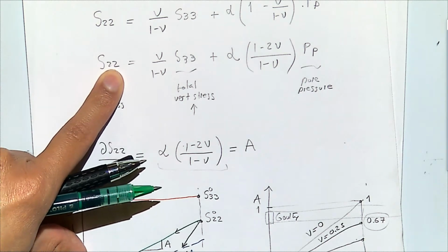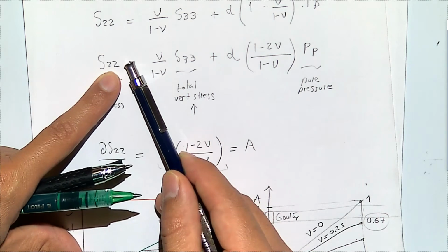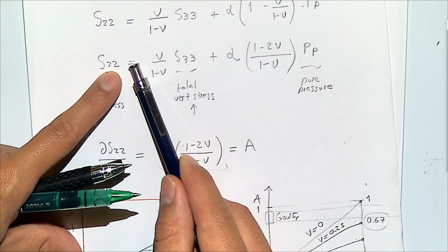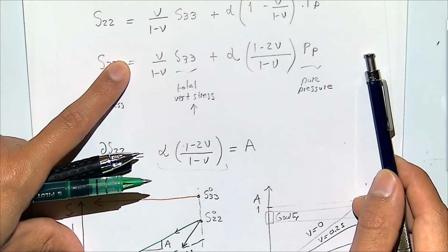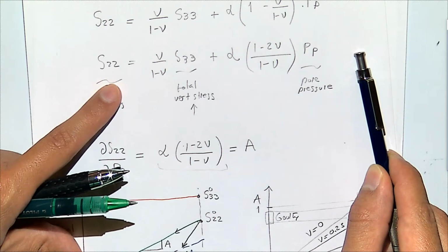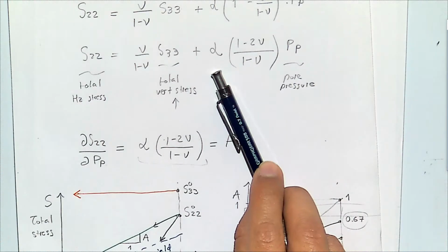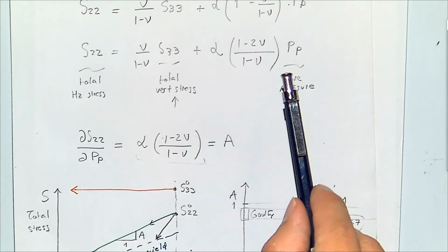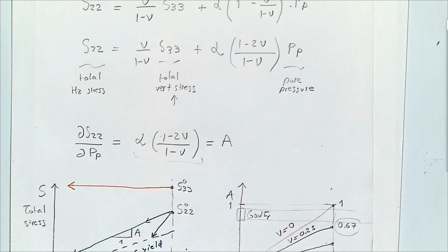So if I want effective stress, I just have to subtract alpha p. So the variation of that, subtracting also alpha p over here, since this is going to be negative alpha and I have an alpha here, it's just going to be this coefficient minus 1, right?